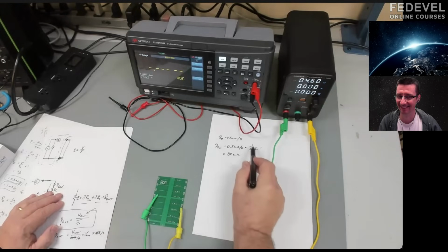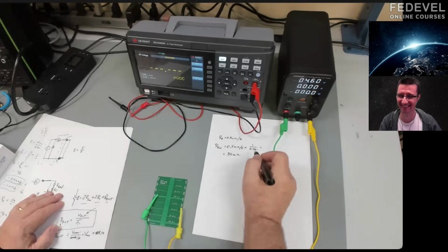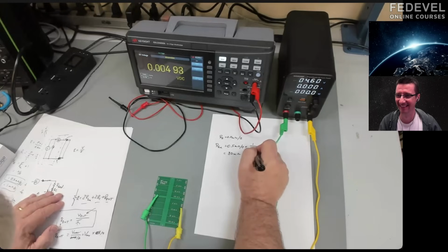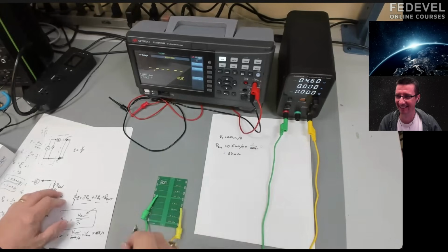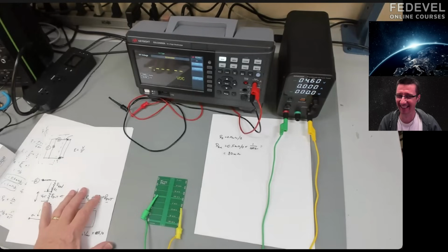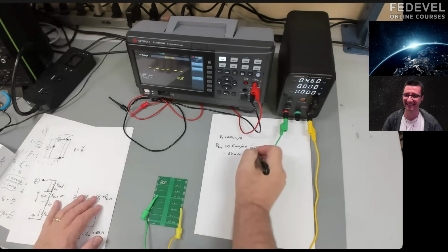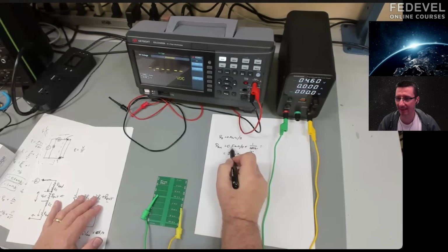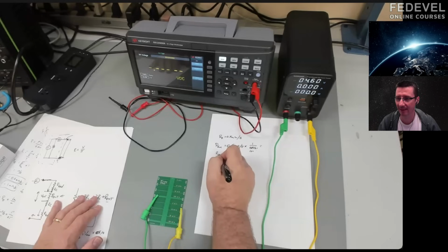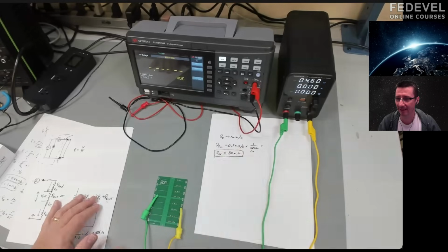I trust you. 1 inch over, oh, I'm sorry. I'm doing this too fast here. I tell my students I make mistakes on purpose for them to catch, but sometimes they don't catch it. So it's 6 mils, so it's 0.006. So this is 1 over 0.006, 160. 0.5 times 160, that's the 80 milliohms. So we expect the resistance for the 6 mil wide trace to be about 80 milliohms.